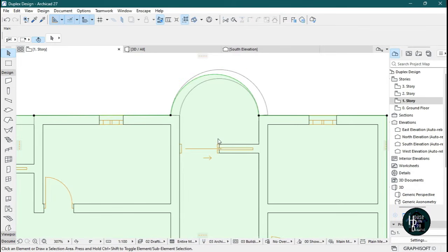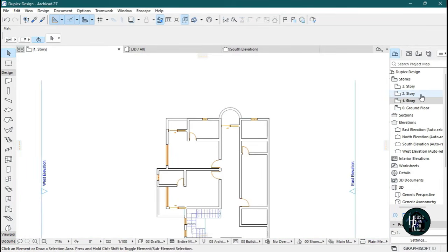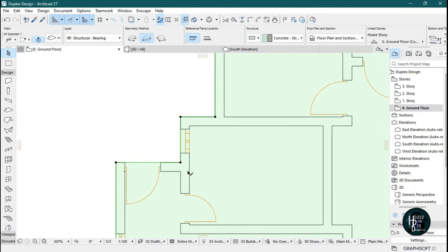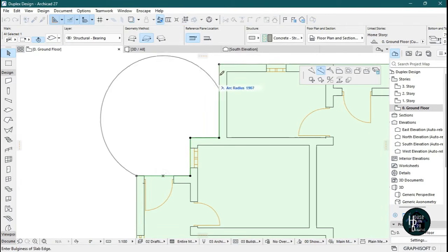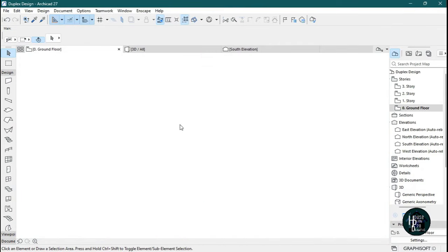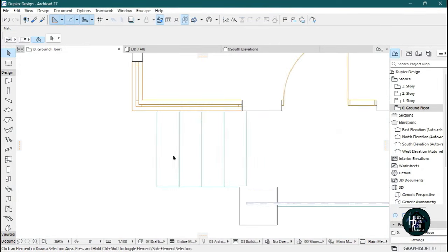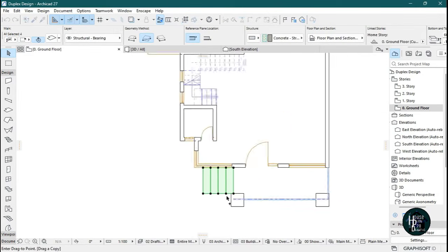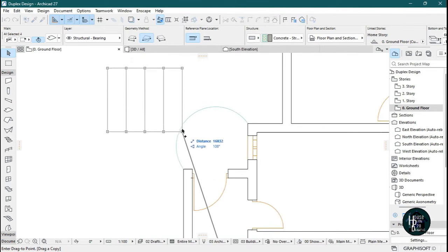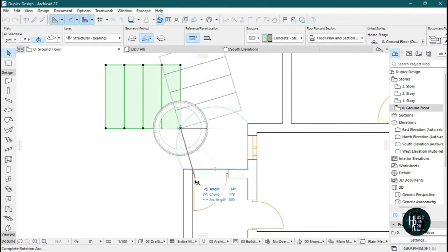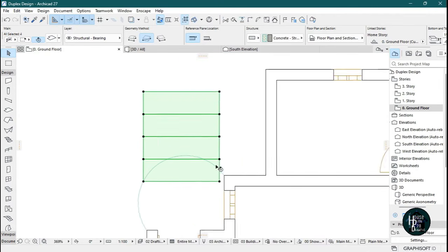So if I go to the first story, let's go to the ground floor rather, so we can work on that. So click this and I'm just going to stretch this out. Yes, he is also going to have his own stairs. So if I pick this one here, click on it, hold down shift, click this, press Ctrl Shift D, and let's make a copy here. Press Ctrl E so that I'm having it facing maybe somewhere straight like this.